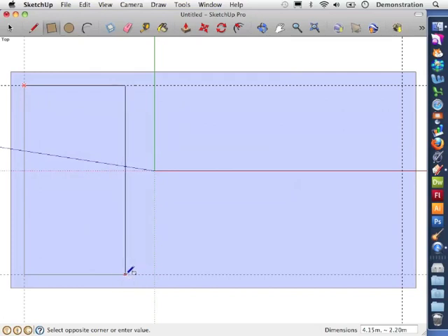And again I'm looking for a width here of about 3.5 meters, in fact exactly 3.5 meters because that's what it says on the plan. But again I don't have to be precise in dragging this out, because I can click and edit the size of the room. Now I have to do this straight away, otherwise it won't work, and I'm also going to remove that little tilde because that can mess up the measurements. So 3.5 meters, press return, and the rectangle resizes to the exact size we want the room to be.